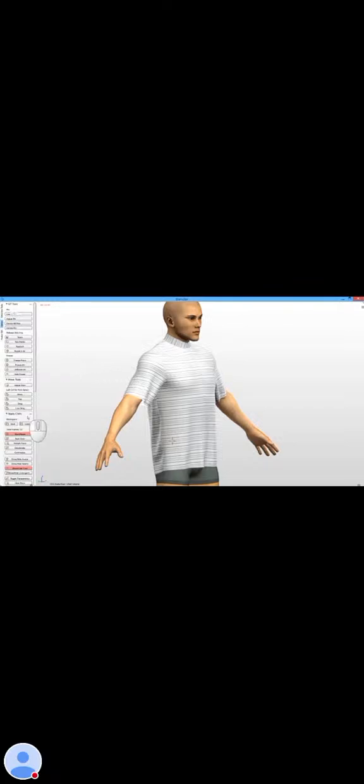Let me make my buttons bigger again. There you go. To do that, I just make sure my cursor is pointing here. To make the buttons bigger in Blender, temporarily, what I can do is just point my cursor here and then use the minus and plus key on your number pad. It'll make your buttons bigger.